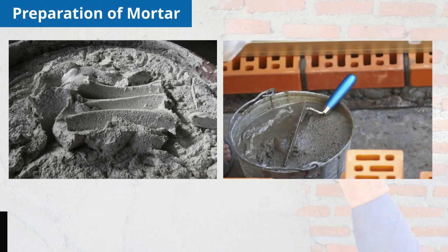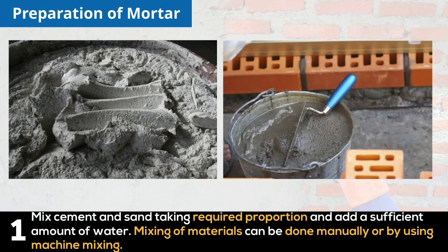Preparation of mortar. Mix cement and sand taking required proportion and add a sufficient amount of water. Mixing of materials can be done manually, or by using machine mixing.